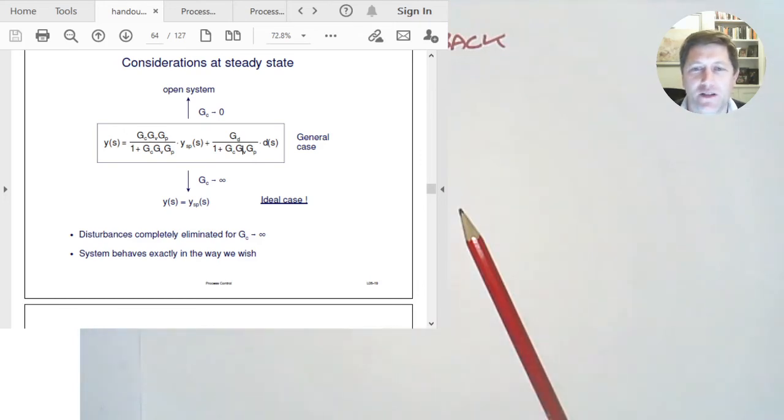Well, this is based on a model of the system, and our model isn't perfect. We know that. We make assumptions about the transfer functions of the process. We approximate them as delay plus first order response when that's not actually exactly what's happening. And so that means that if your process doesn't actually quite match your theory, and you've got a whopping great gain on your controller, then it's going to behave very dramatically when there's any small deviation from the ideal theoretical behavior.